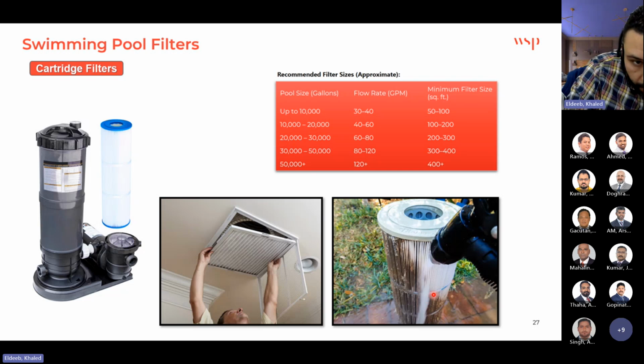So the sand filter usually is enough for the pool. No need to provide a Cartridge filter, but if you need it, it doesn't cause harm. And the sand filter is sufficient for whatever you need to design the swimming pool.